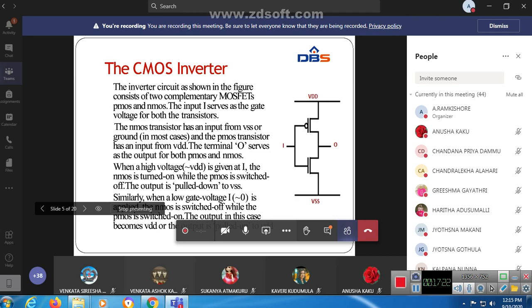But the chips from different logic families, for example in a single circuit we are connecting an op amp, operational amplifier, and another digital IC that came from a different logic family, may not be compatible, and they may use different power supply voltages or different input and output conditions to represent the logic value.